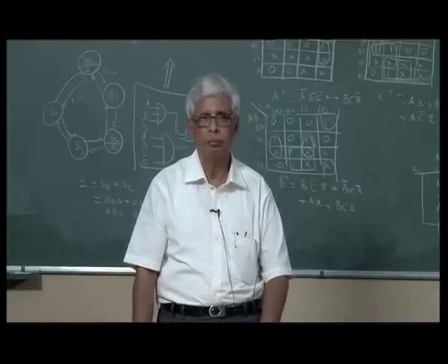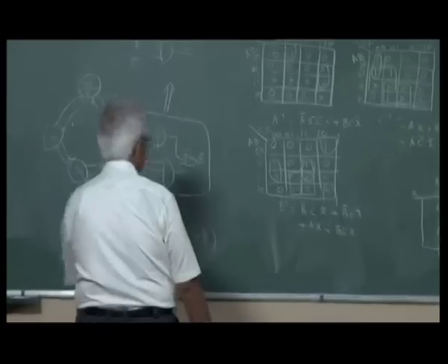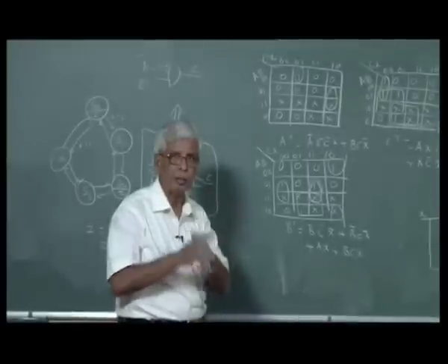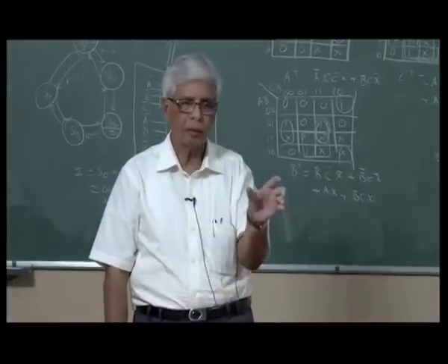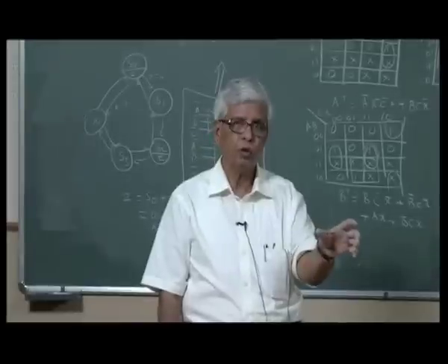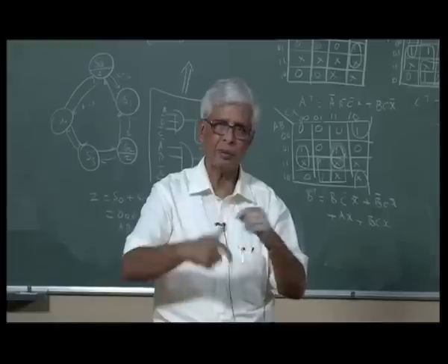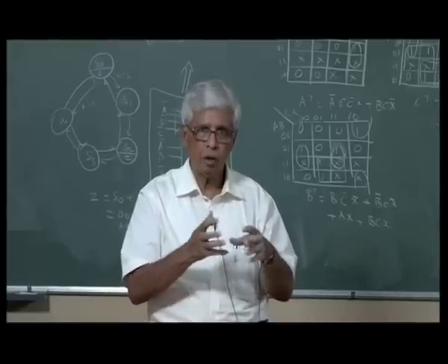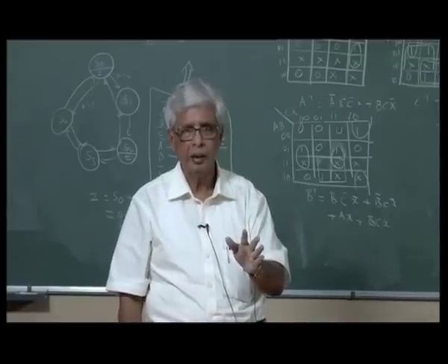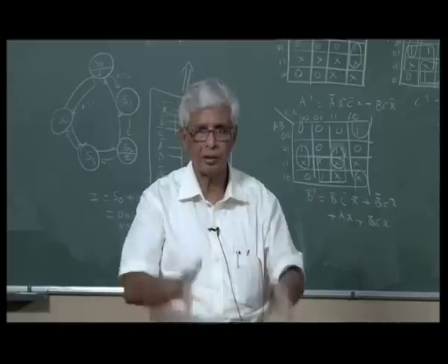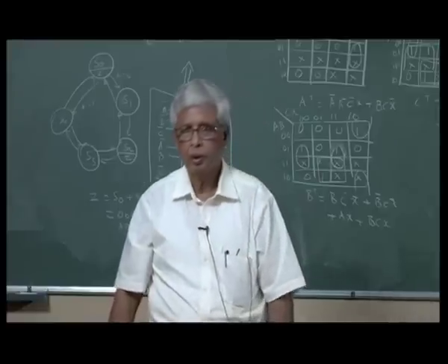That is an example. Suppose you want to delay by 4 bits, or you want the data to remain there and take it whenever you want. You apply a clock gating pulse and take it out. Whenever you want, you have to apply a clocking gate which is 4 clock cycles in duration. At that time you will be able to get the output. So I have this recirculating feature, it keeps circulating. If I do not want to use it, I do not have to. If I want to use it, I will have to give a clock gate of 4 clock cycles duration. Then these 4 bits will go one by one to the next register. This is for delaying purposes.